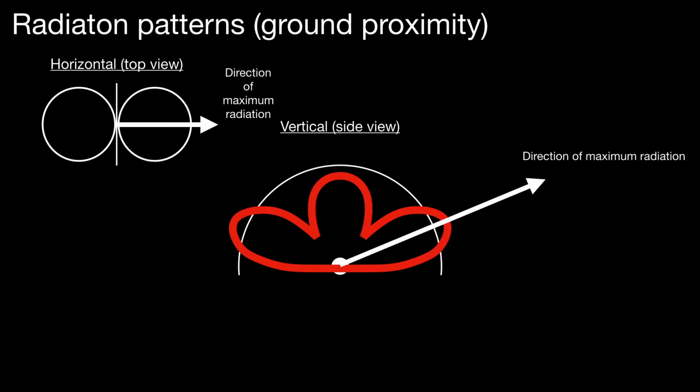If you look on the internet, there are some diagrams of horizontal and vertical antennas at various heights, and it depicts the lobes. There's not always just three, sometimes multiple lobes are established as you raise and lower the antenna, and the picture changes. But the main lobes, the direction of maximum radiation, as you raise the antenna, the angle of incidence then drops down, so that the takeoff angle is flatter, and that's a point to remember.